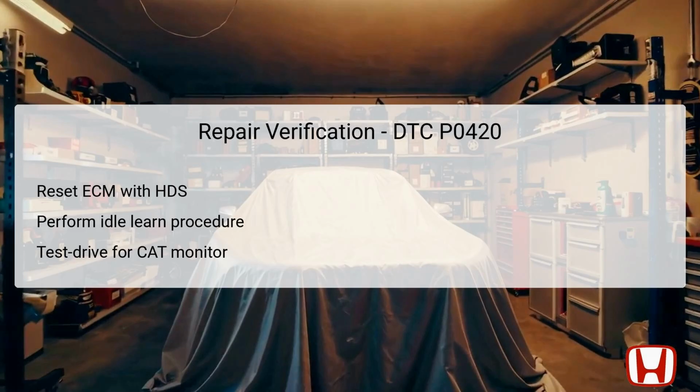Following this, perform the ECM idle learn procedure to help optimize the air-fuel mixture settings based on the newly replaced or repaired components. After these steps, conduct a test drive lasting at least 10 minutes to allow the catalytic system to complete its monitoring cycle.